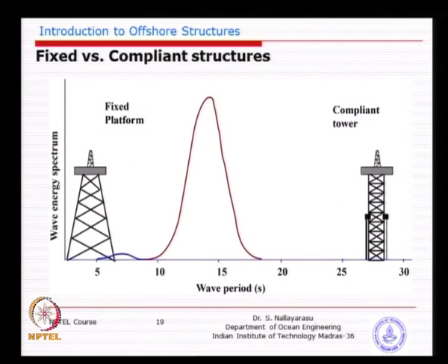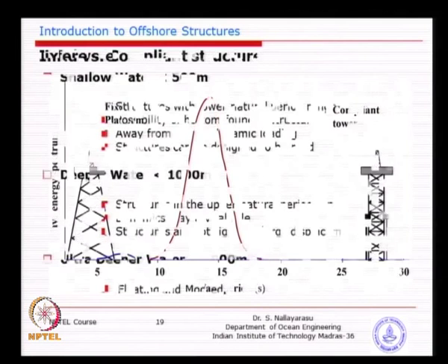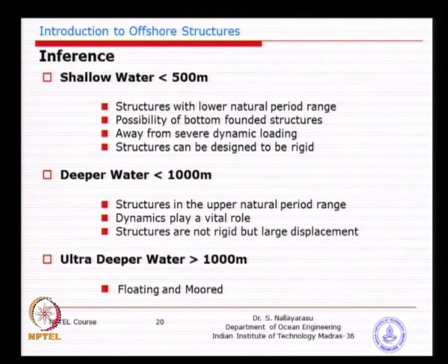Something similar is given in period, fixed versus compliant. So, most of the energy content of the wave will be between about 10 seconds to 16 seconds, potentially a very large energy magnitude, whereas the fixed platforms we keep on this side, and the compliant tower or floating systems go into the other side.